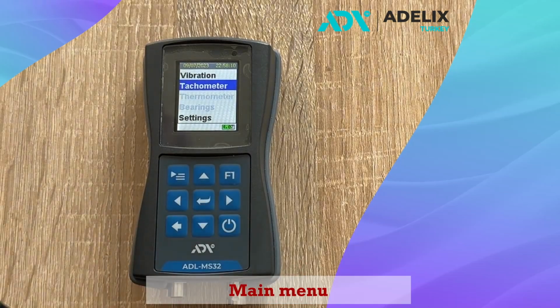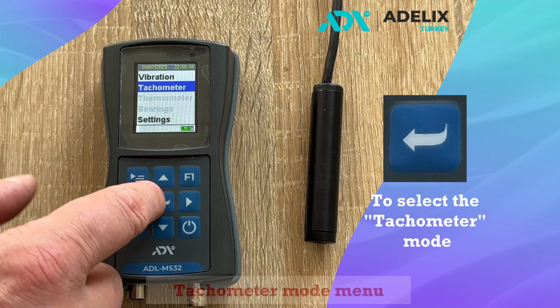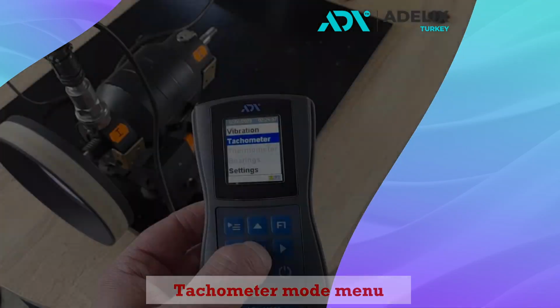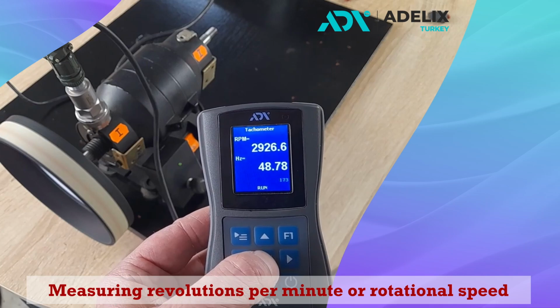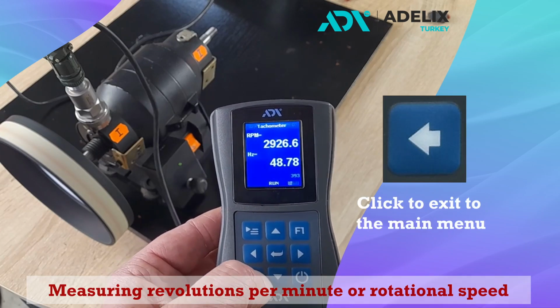Next, we select the tachometer option and confirm it by pressing the button. To operate this mode, you need to connect an optical sensor. Afterward, press the input button, and it will start the revolutions per minute measurement mode. The instrument's display shows measurements in revolutions per minute and rotation frequency.